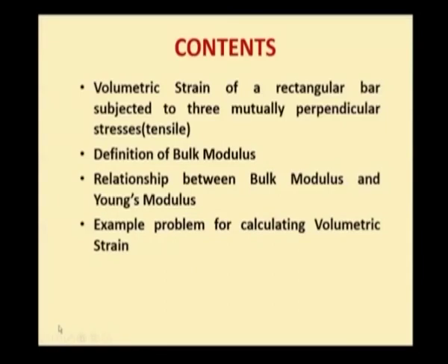We will be calculating the expression for volumetric strain of a rectangular bar subjected to 3 mutually perpendicular tensile stresses. Next, we will be seeing the definition for bulk modulus. Then we will be obtaining the relationship between bulk modulus and Young's modulus. Finally, we will be seeing an example problem for calculating volumetric strain.